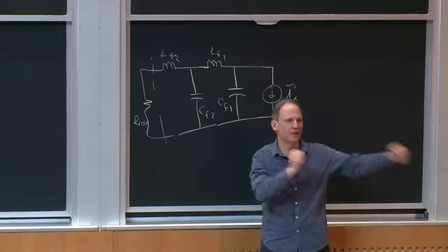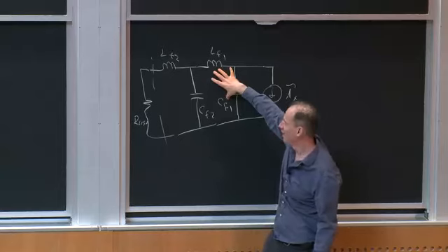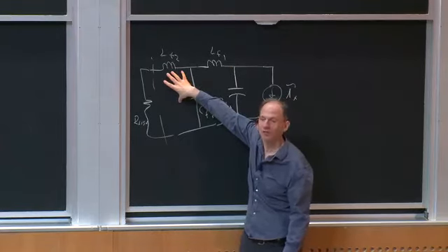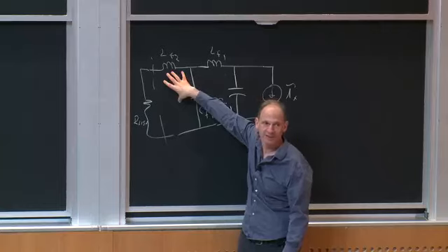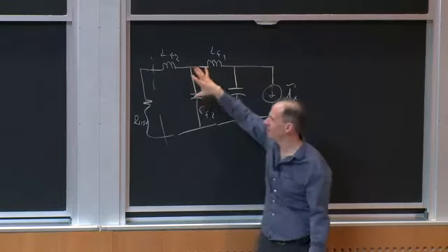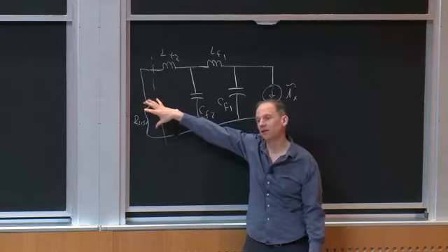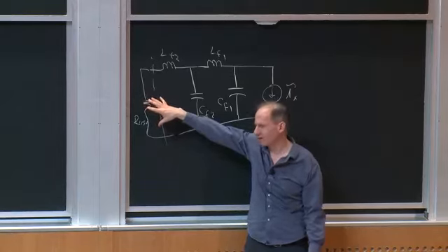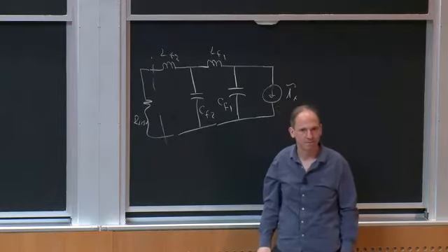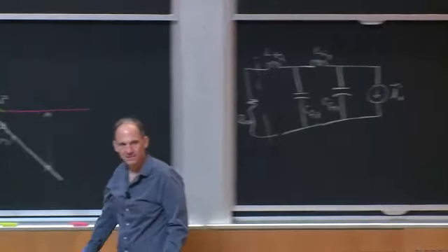It turns out to be better to stagger these things. So usually you'd make this one a low cutoff, and then this one a higher cutoff to deal with the higher frequency and so forth. It turns out to be a better design strategy for these kinds of filters. Okay, so you can cascade filter sections until you get the attenuation you need. And if you look in a typical offline power supply that you'd plug into the wall, they usually have a couple filter stages like this. Okay? Any questions about that?